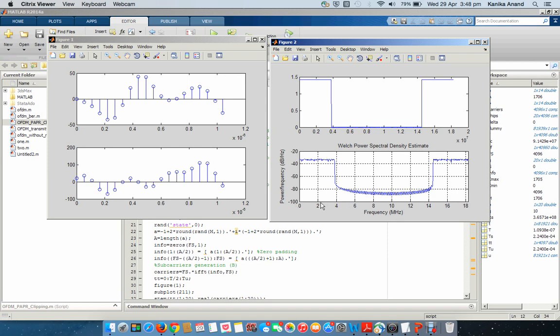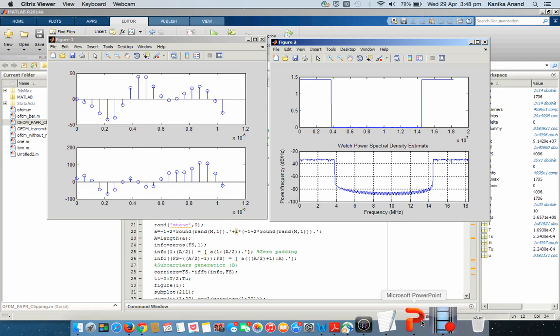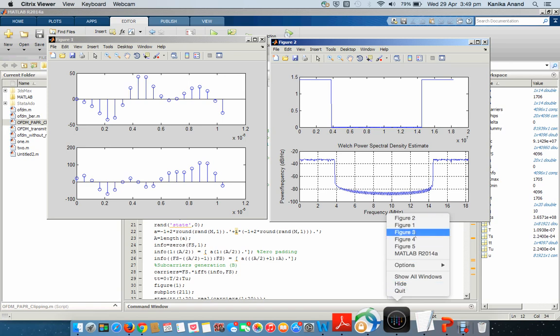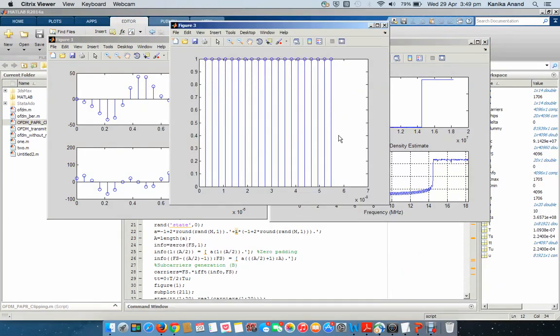We could use this signal in baseband discrete time domain simulations, but we should recall that the OFDM drawbacks occur in the continuous time domain. So the first step is to produce a continuous time signal by applying a transmit filter GT to the complex signal carriers. The impulse response, or the pulse shape, of the filter GT can be seen here.